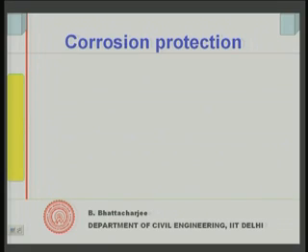So, what we have seen in case of plain carbon steel, generally we use mostly mild steel, which is less than 0.25% carbon, and normalized steel quite often, because we also need machinability.